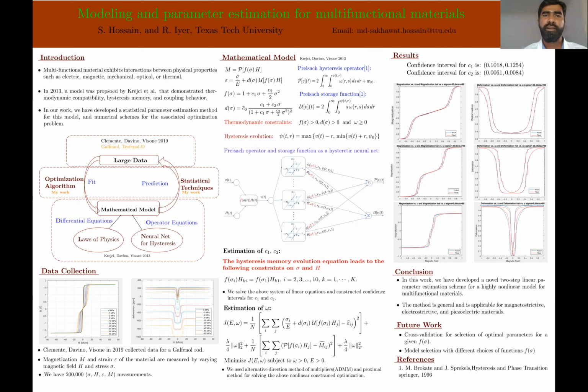The main difficulty of the problem is that the model equations are highly nonlinear, and they are in terms of double integral operators, the Preisach hysteresis operator, and the Preisach stress function. Here, the input itself is the product of a nonlinear function f of sigma and the magnetic field H. The hysteresis memory evolution makes the problem more complex. It has both forgetting and remembering properties of the memory.